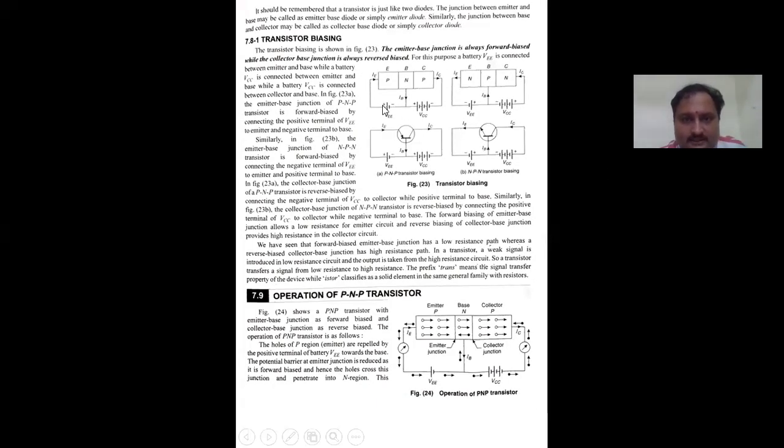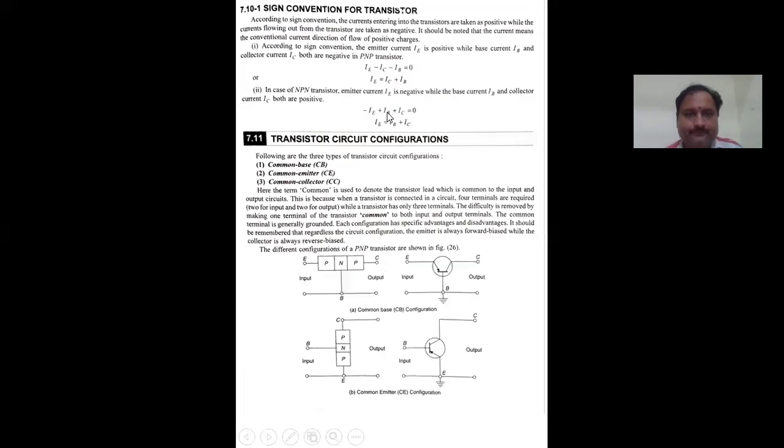This is the input and output characteristics circuit. We are applying input, which means we are increasing the values on this side. This voltage must be constant. We are varying these values. This battery must be constant. We observe this in three different cases. At collector-emitter voltage VCE of 1 volt, we get this graph. For 5 volts, we get this type of graph. For 10 volts, this type of graph.